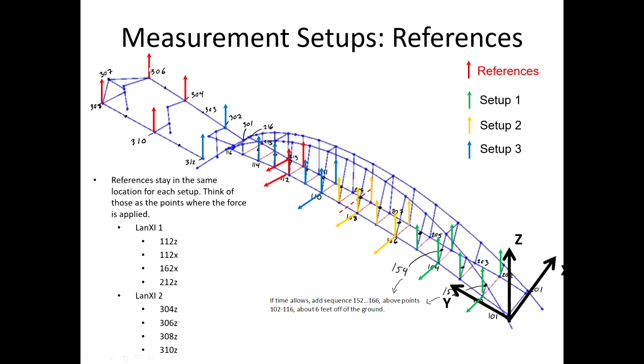And then a set of sensors on the ramp. I said the ramp motion was important, so we'll watch that always so we can see the connection between the ramp and the rest of the bridge. So we'll have a 4-channel box going to each of these spots and measuring in each of those sensors. Assuming our cables are long enough, we'll adjust when we get there if we have to.